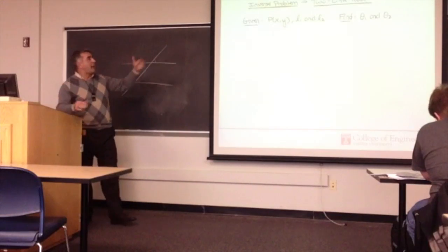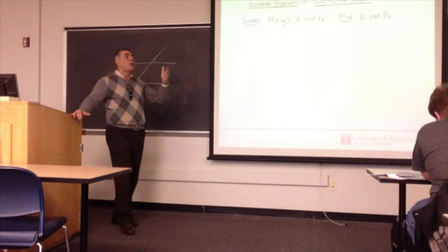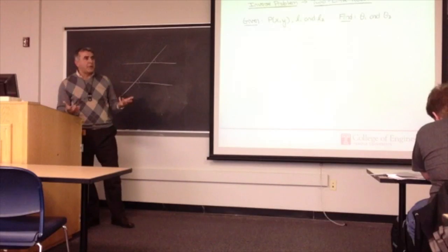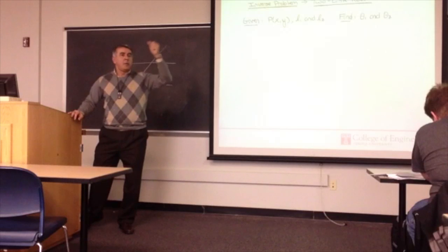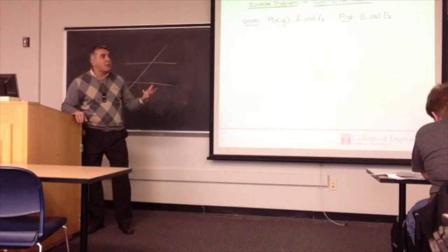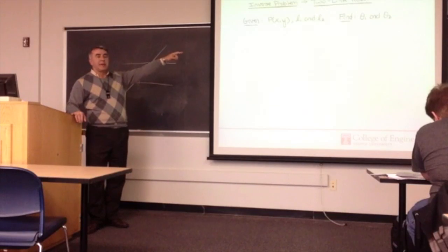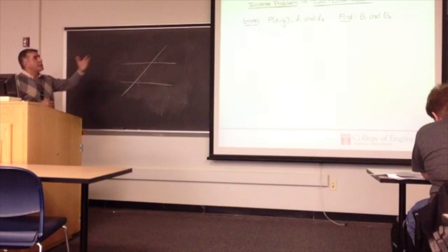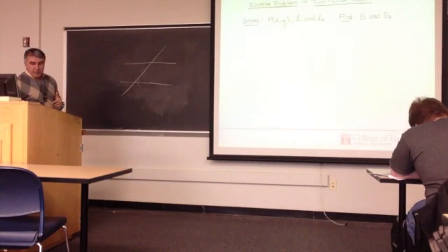Before, we had L1 and theta 1 and L2 and theta 2, and we wanted to find where it ends. But in the day-to-day operations of a robot, you know where you want to go, but what you don't know is how your motors must act. That's what we are trying to find out, theta 1 and theta 2. Do you understand? The inverse problem is more of an application than what you had before.